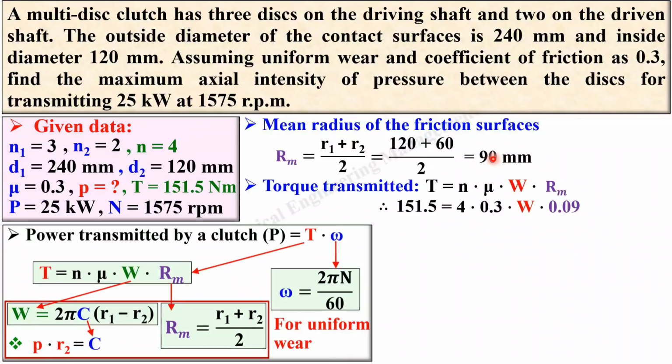But here, a very important point: Rm is in mm, but you should put the value of Rm in meter, because in this equation torque is in Newton meter.